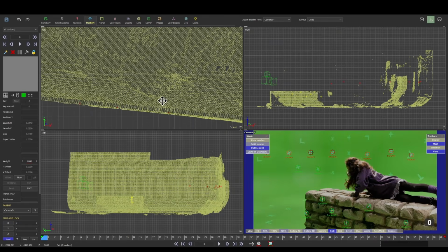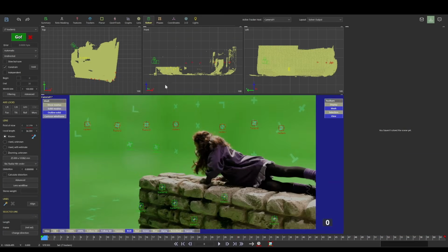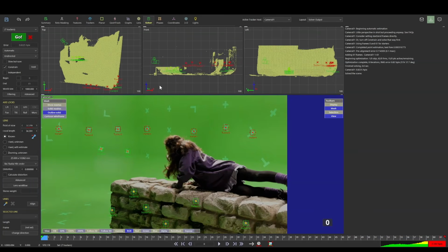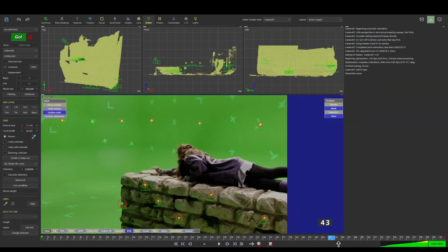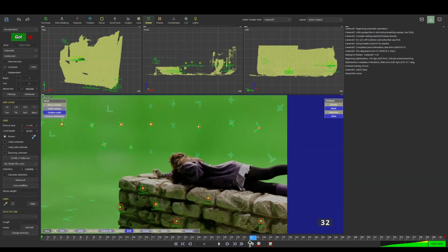You can see the kind of the red spots here. So now we can see where our camera is, and then when we go to our solver, we're going to click solve, and now the shot is just solved. We can see that the tracked points have stayed there, the camera's moved slightly, and the overall shot is doing reasonable. It's about 0.823 pixels of error. And we want to make that a little bit better. And it looks like the larger error is coming in toward the end.